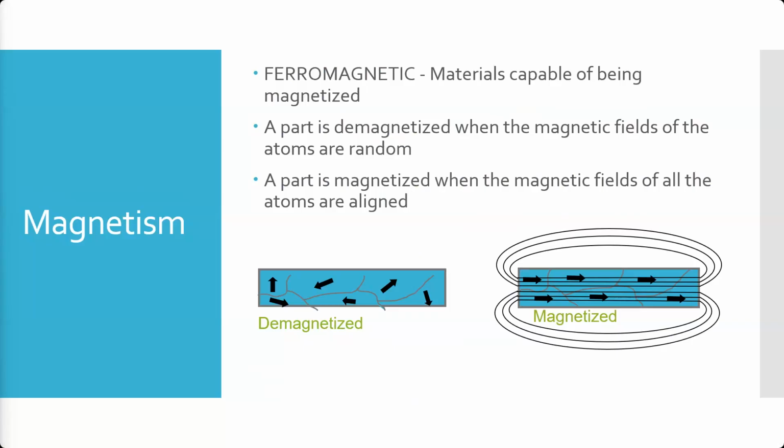And if we dye those magnetic powders with a fluorescent dye and then point a black light at it, or if we dye them with colors in certain systems, for visible light, then we can see where those particles collect. And that is the idea behind magnetic particle inspection, where we get that flux leakage.